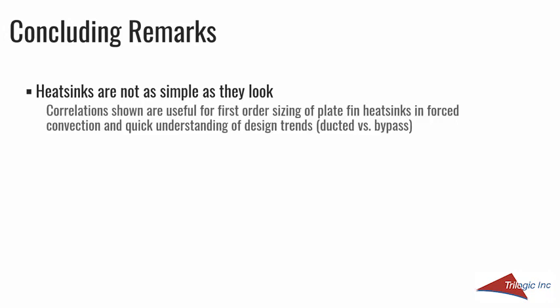The correlations shown are useful for some initial sizing and studying of the trends between some design choices, like ducted versus bypass, more fins versus less fins, heatsink length versus heatsink width. But you certainly wouldn't want to base your final design on correlations, I don't believe. Not today.